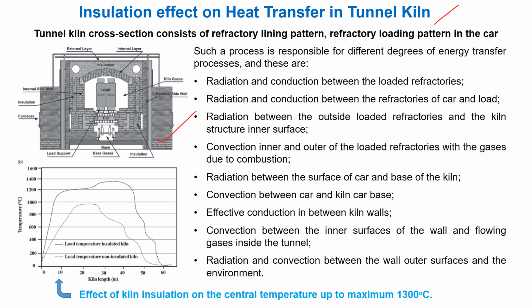A prerequisite temperature may assist in developing proper firing that eventually develops ceramic bonding strength and defect-free refractories. Thus, herein pointed out all probable heat transfer processes during firing, for example, radiation and conduction between the loaded refractories, radiation and conduction between the refractories of car and load, radiation between the outside loaded refractories and the kiln structure inner surface, convection inner and outer of the loaded refractories with the gases due to combustion,